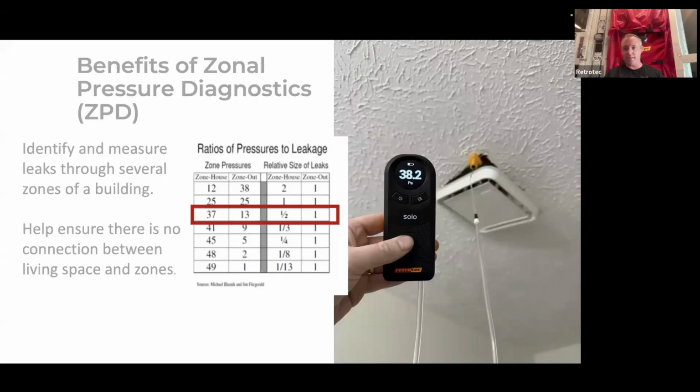If we were in a cold climate, that would be a big driver for ice dams. But this house is in a warmer climate, so it wouldn't see that. What these implications really mean a lot of times has to do with where you live. But in this case, in the summertime, when we get that reverse stack effect, we're just pulling in 140-degree attic air a lot of the time. And so we're making our HVAC system work way harder than it would have to otherwise if we had an airtight ceiling plane. So this is just a way that we can spot check that.